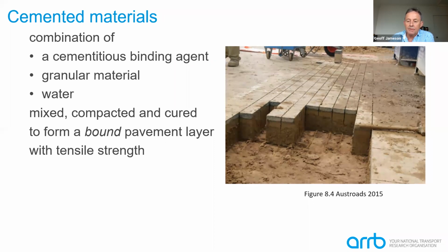Shown in that photograph there is a test site where we've been doing accelerated loading, looking at the performance of cemented materials. After that accelerated loading, we cut some beams from the pavement and did some testing for modulus and fatigue that we'll talk about later. But you can see how the material forms a block. It's bound together.